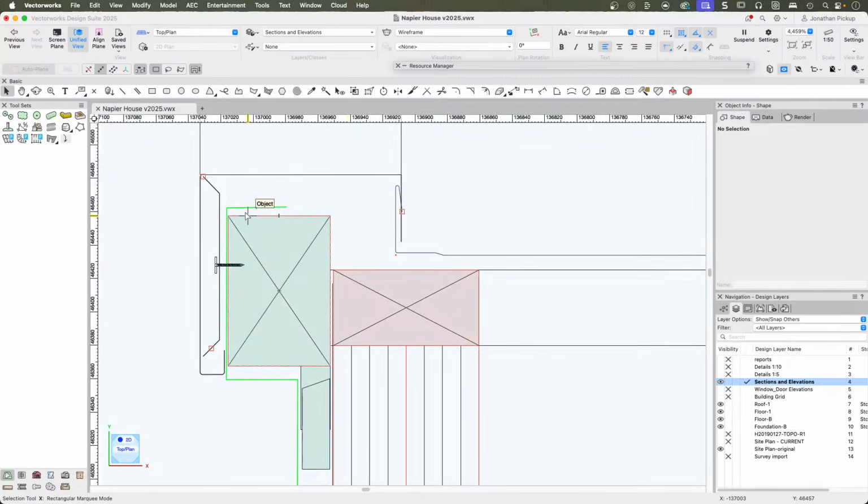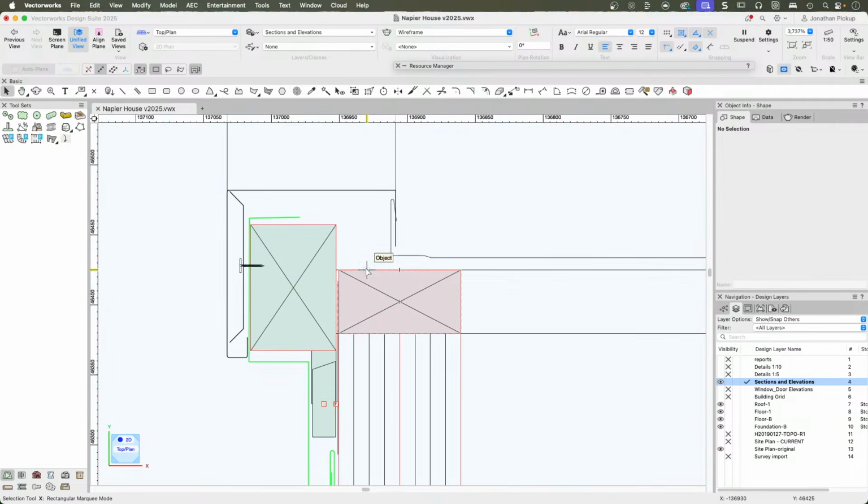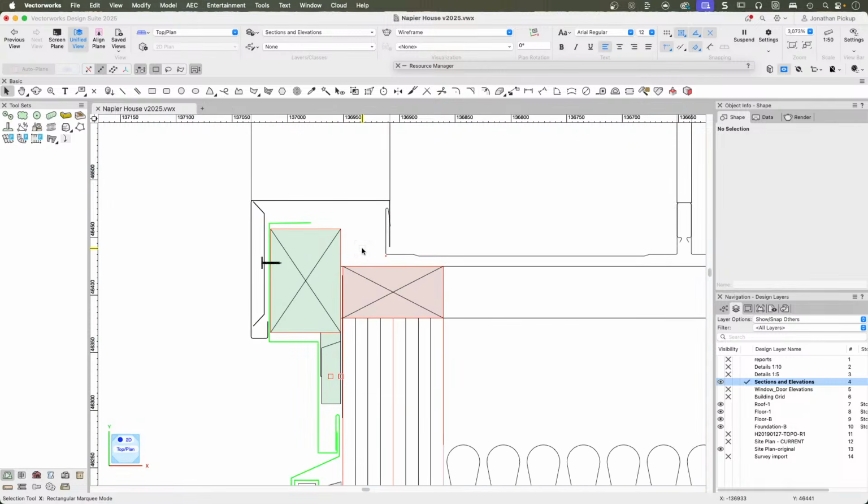But notice that I've given a little bit of white space between that material and the next one, and between that flashing in here, and between that piece of timber. I've taken a whole lot of steps to make sure that my flashings and my objects are readable. They're separated. In details, I have to make sure that they're even more separated. But I'll take this information and copy it to my design layer, where I'll then create my details.